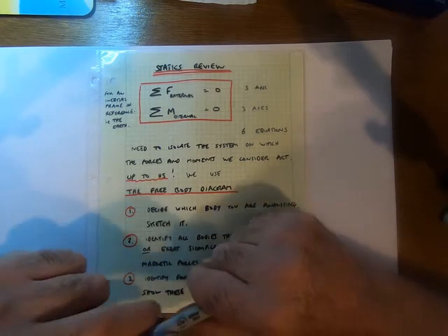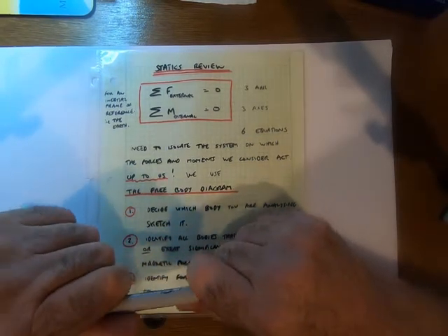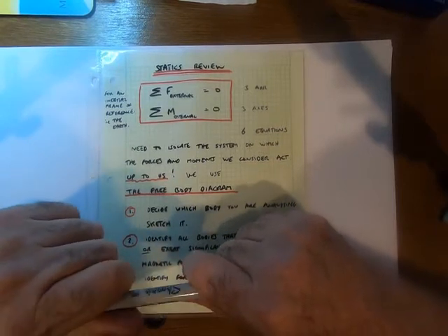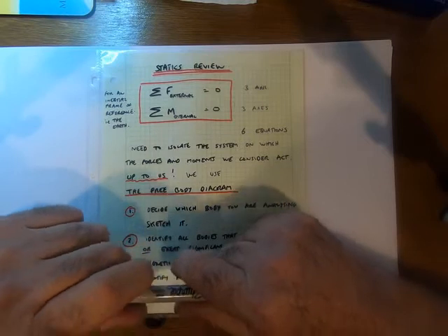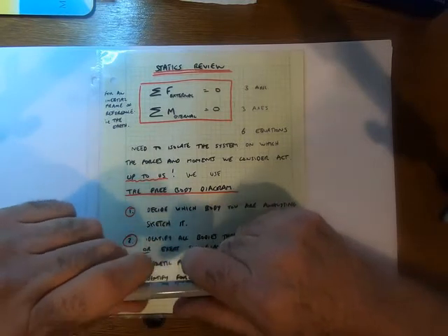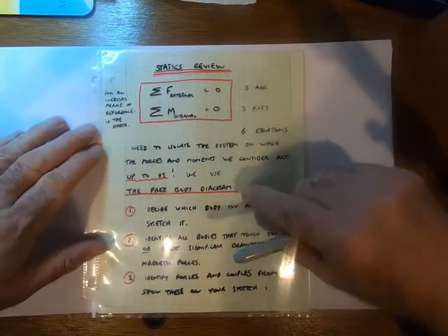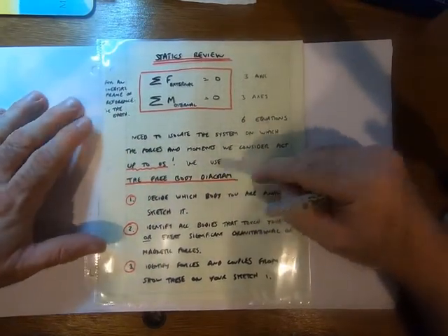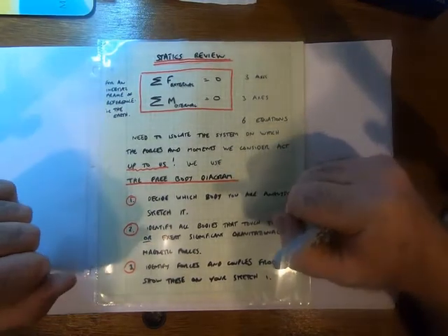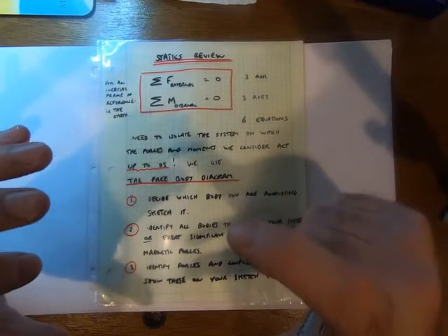If you're going to draw a body with forces on it, show all the forces and make it clear that it's a statics problem, they're equal to 0, or show the resulting accelerations. Okay, otherwise you're only telling 2 chapters of the 10-chapter story. You need to show all the forces on a free body diagram and make it clear that what you're showing is a free body diagram. So with free body diagrams, basically we decide the body which we're going to analyze, and then we look at that in isolation.